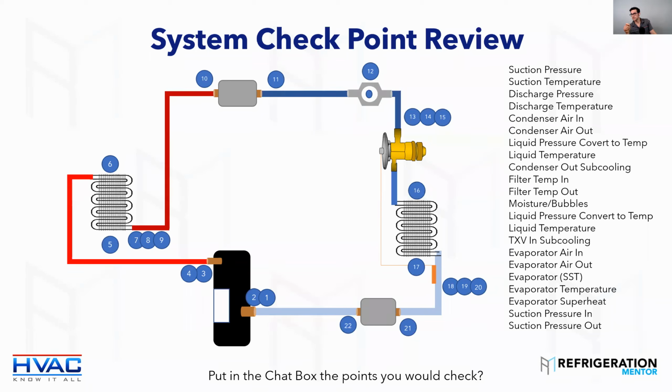Very important. What do you think, Carrie? Do you do that? Do you put that in your quotes to follow up? You know what? It's funny. I think last year I changed 1 or 2 compressors in total, and one was a bad burnout. And the only reason I knew it is because we did an oil analysis. We did an acid test. And because of that, we put in an acid suction dryer. And it hasn't been taken out yet, but it's being monitored.